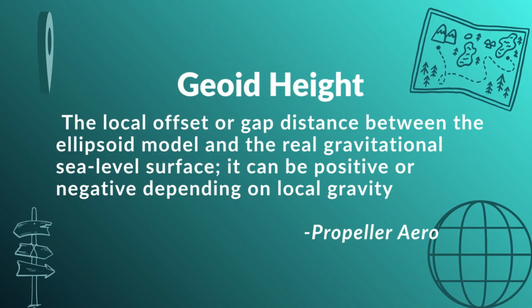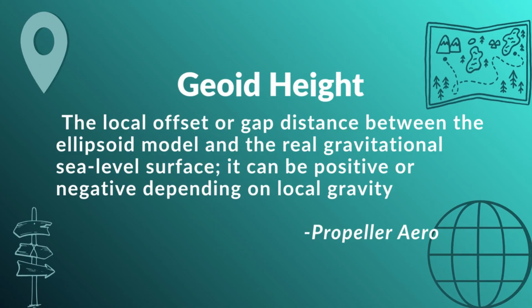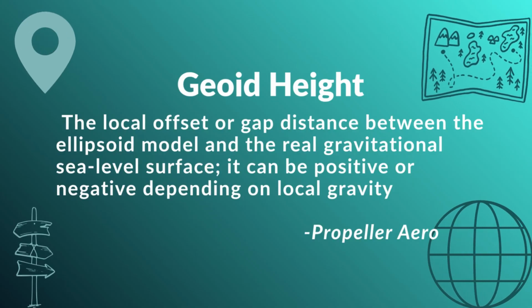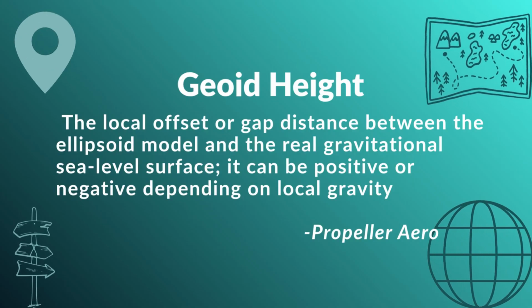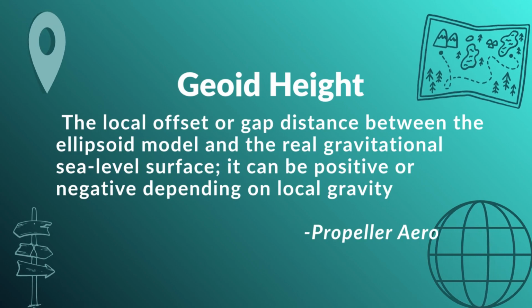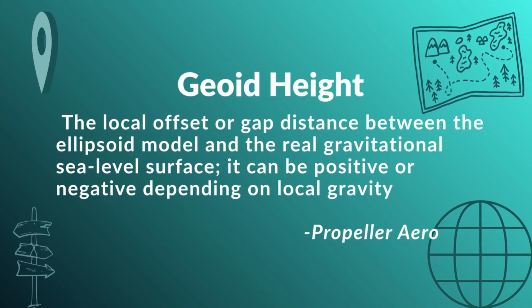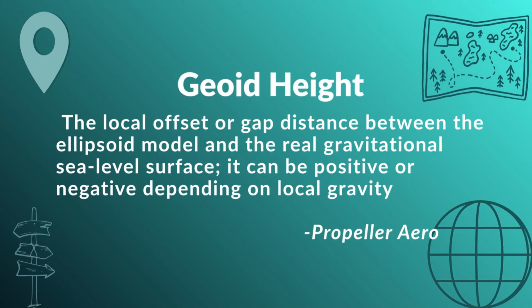That's it exactly. For everyone listening, if you want a reliable strategy to lock this in for the GISP exam, just frame geoidal height in your mind as the gap between math and reality. Oh, I like that. That is a perfect mental hook. The gap between math and reality. And keep in mind for the test that geoidal height can be expressed as a positive or a negative number.